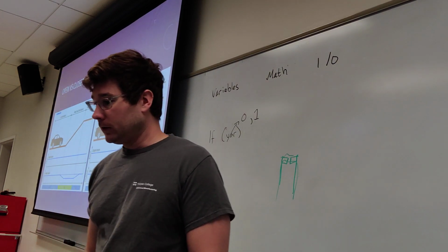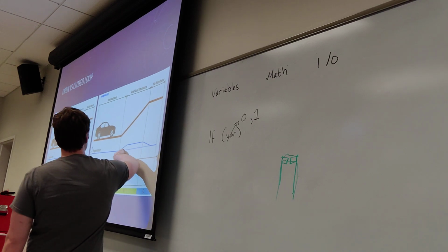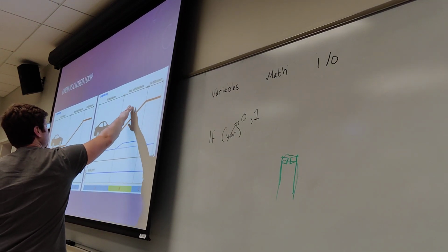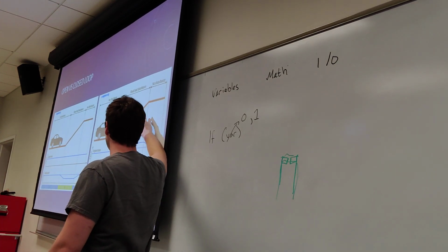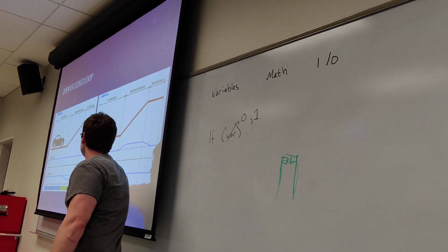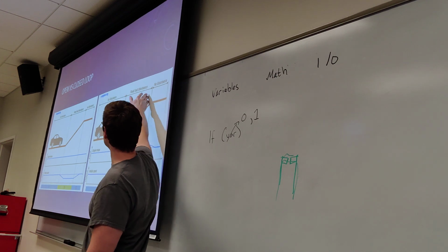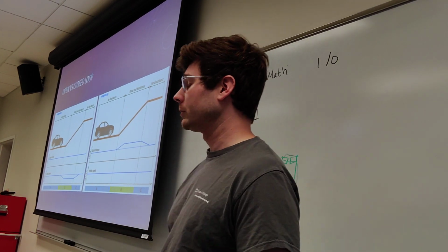Closed loop, we can see that the engine starts to work harder. We get some road disturbance, we can see that change in speed or the change in torque on the motor and compensate accordingly. The vehicle speed does not change, where the input torque, or the amount of power that we use to get up that hill, does change. It responds accordingly.